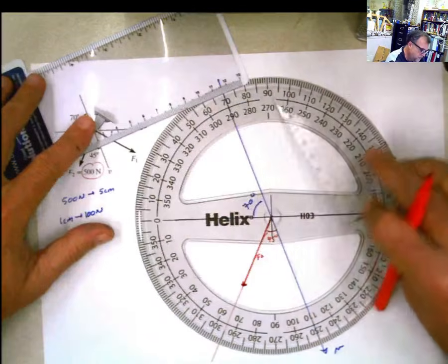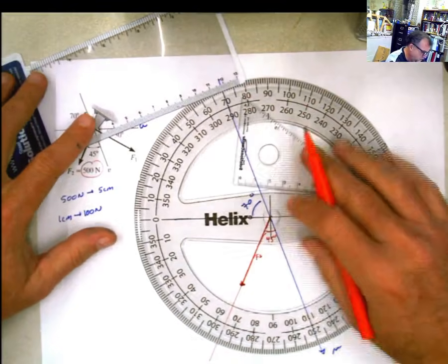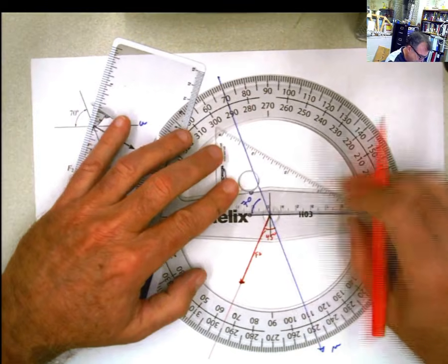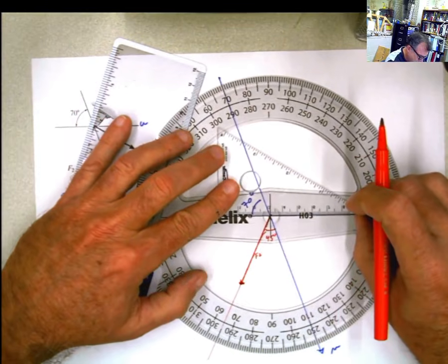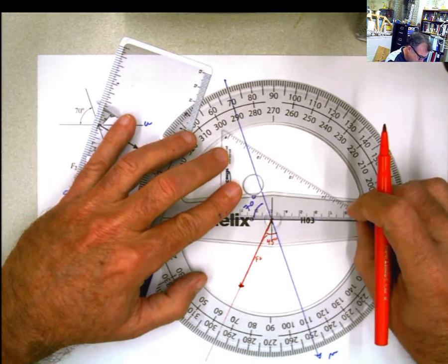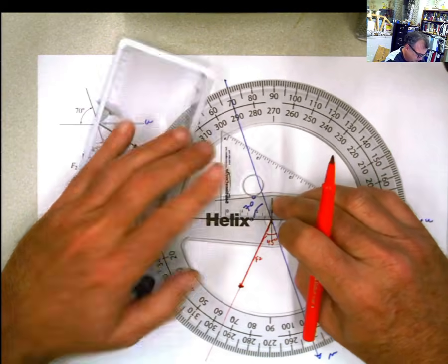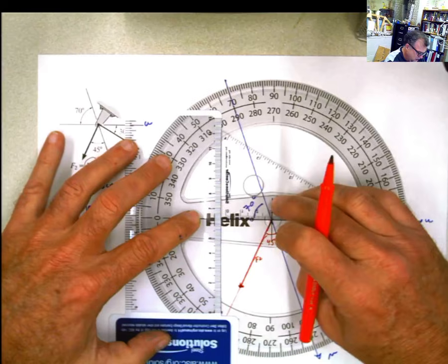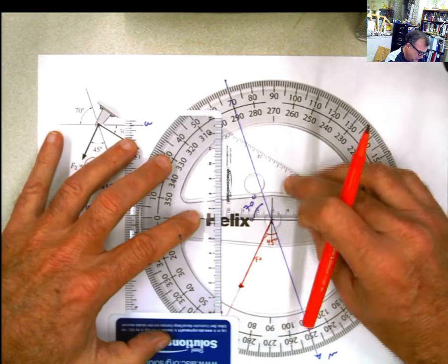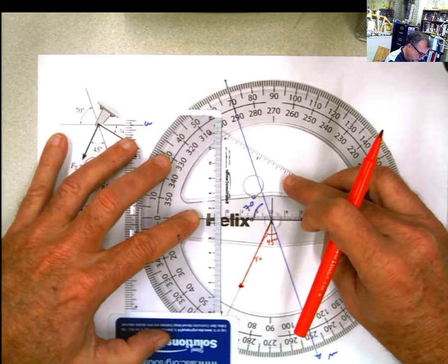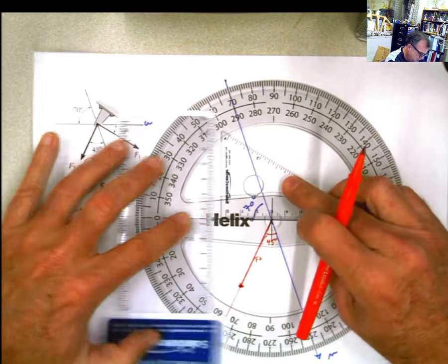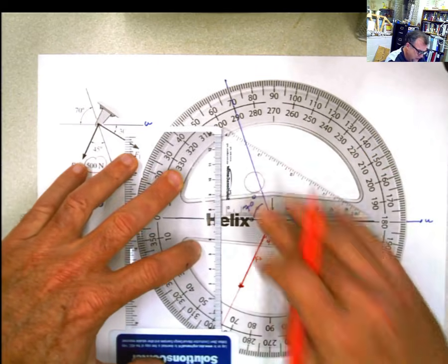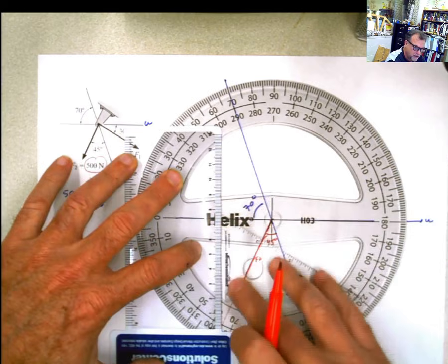You have to draw a parallel line. How you draw a parallel line is pretty much up to you. You can use a square triangle like this, a square straight edge. You can put it here, and I know this, if I make a line at this point now, you see I'm putting this here, and with the perpendicular edge here, I'm putting another ruler, and if I keep this fixed now, I can make any amount of parallel lines here.